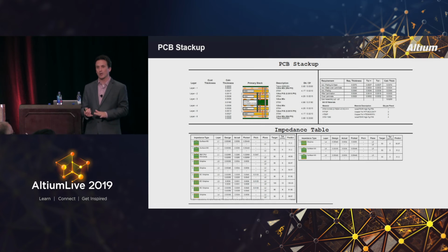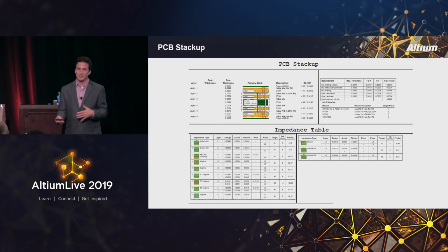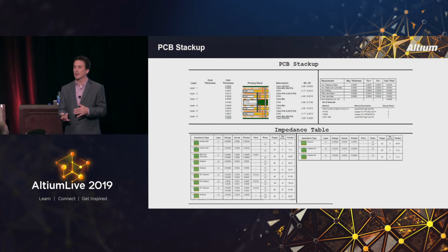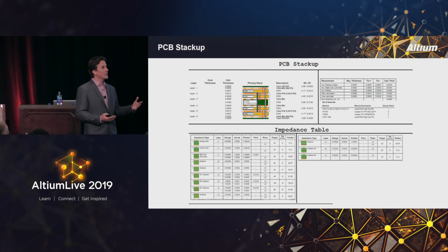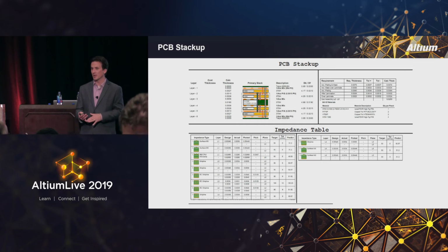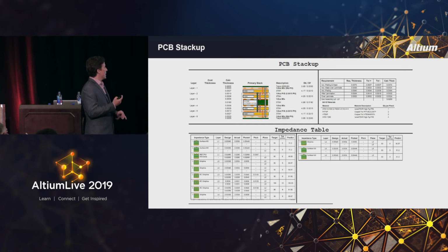It's not just how your signal layers are adjacent to ground layers, how hopefully your power layers are adjacent to ground layers, but it's also talking with your manufacturing about reliability, talking about CAF, talking about your via structure, talking about how the decisions you are going to make affect the reliability, the manufacturability, the cost, and the time it takes to manufacture your circuit board.